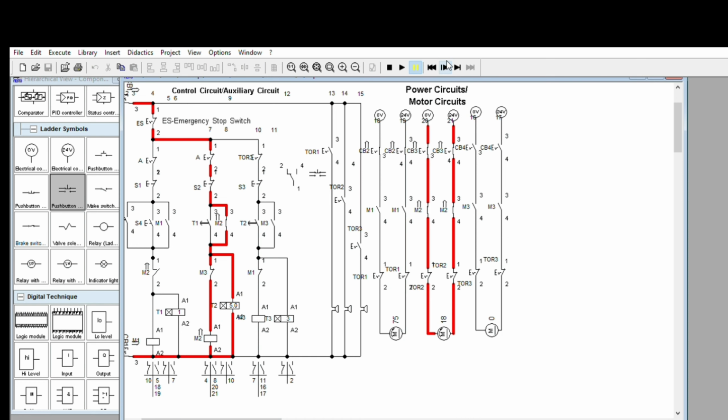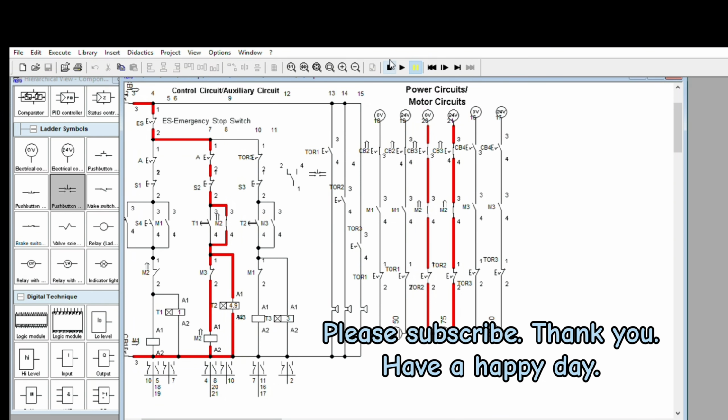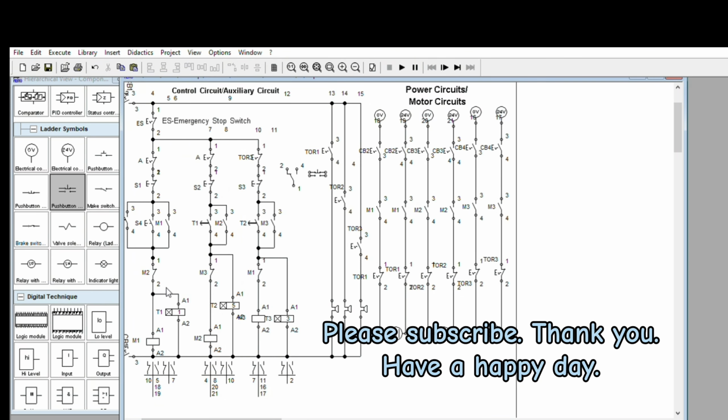Sometimes you cannot see that there, but in reality it will have. You will hear a big impact because there is that instant short circuit. Sometimes the circuit breaker will trip off if you have a forward reverse connection. Because two lines will be short circuited when you maintain one line and interchange the other two lines in forward. So better to connect this one here.